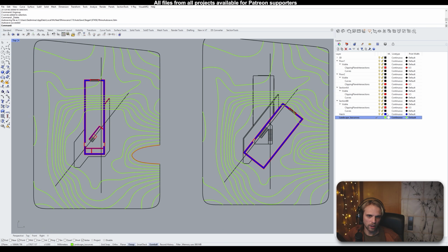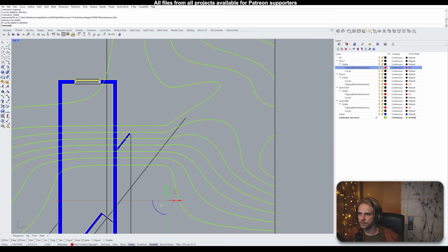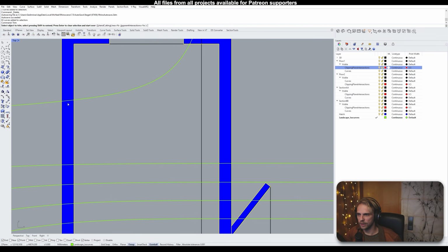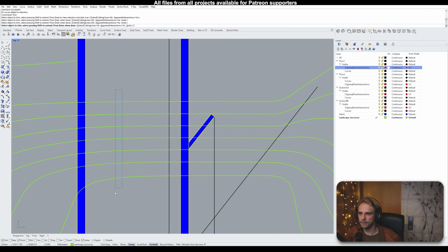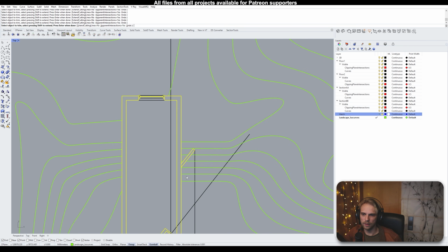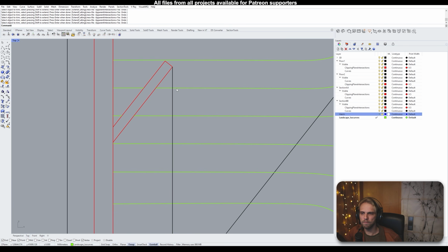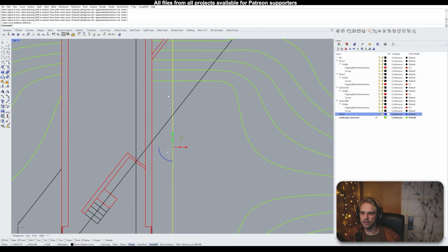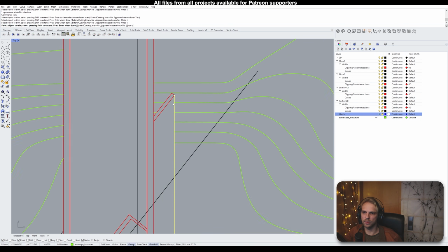As easy as that. So I'm just going to choose clipping plane intersections for floor 1, select objects, type in trim, and go to town, trimming the contours like that. Hatch is in the way, so I'm going to hide the hatch layer so that it's easier to trim like that. Is there anything else here? Not really. Okay. And then this line right here, this is our little terrace that also trims away the contours. So I'm just going to do something like so.